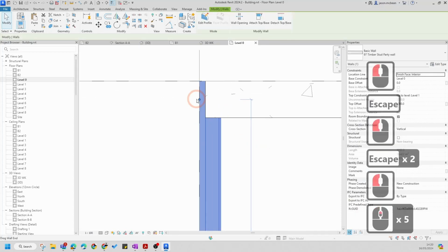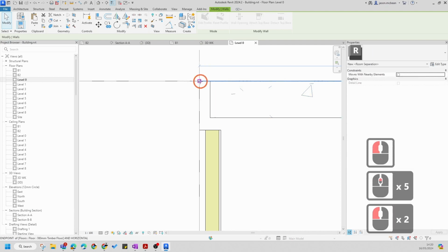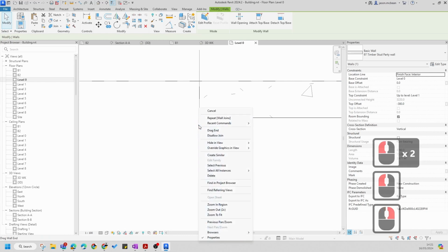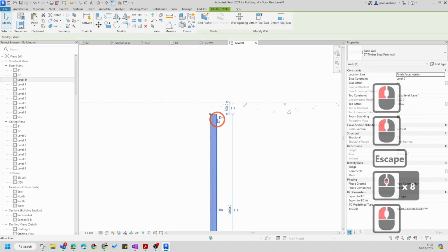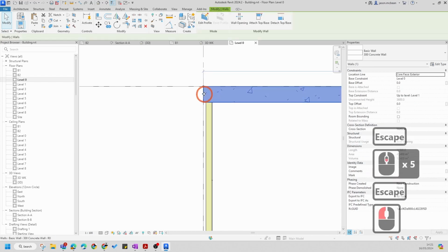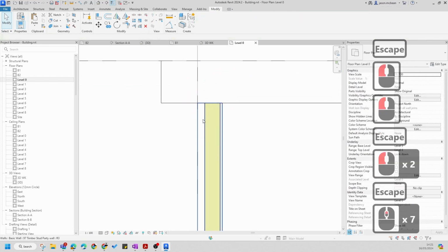Now, in order to circumvent that, pull this in that direction, you pull this like that. Now, when this wall joins, before you join it, you click on this intersection dot. You're going to say disallow join, and you're going to simply snap it to that wall. It's telling you that they're no longer joined. It's just so we don't have that error where we've got that thermal gap. Sometimes you can take this wall past and then you can say allow join, then it works.